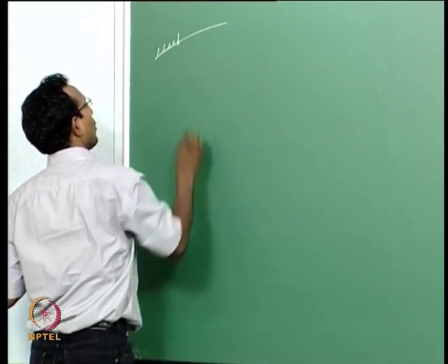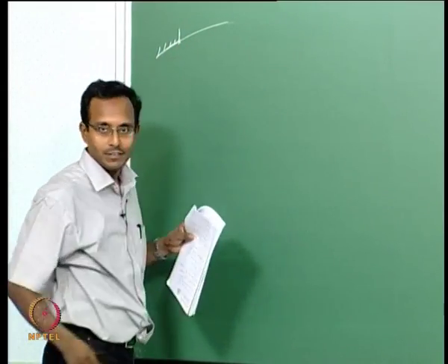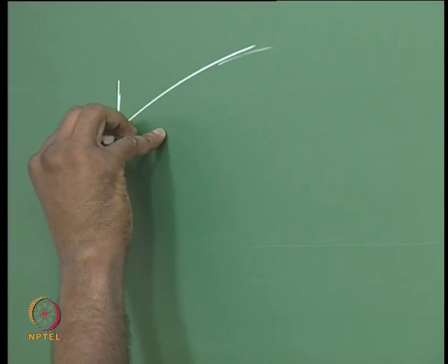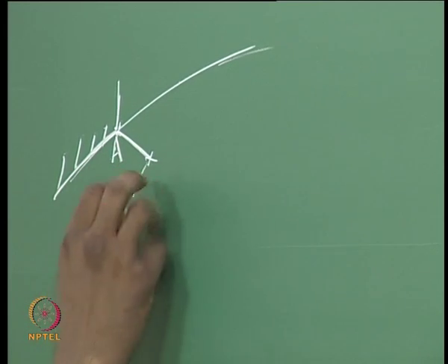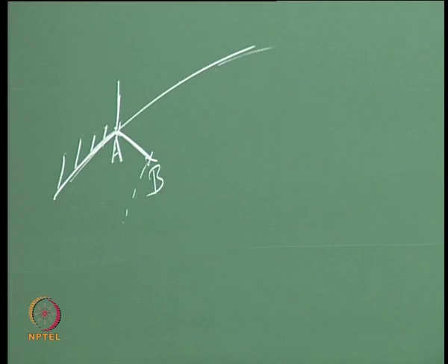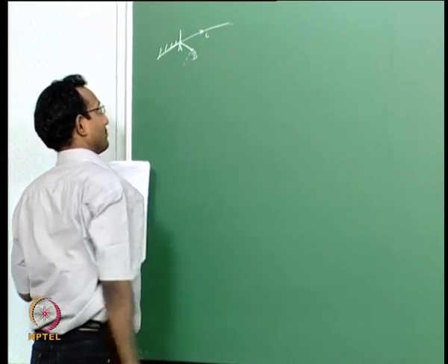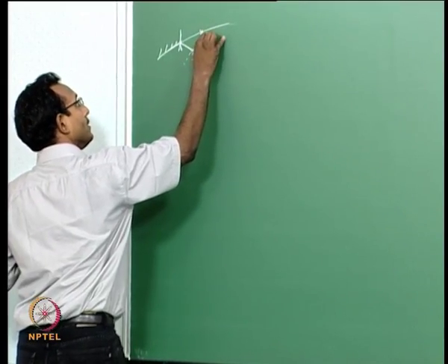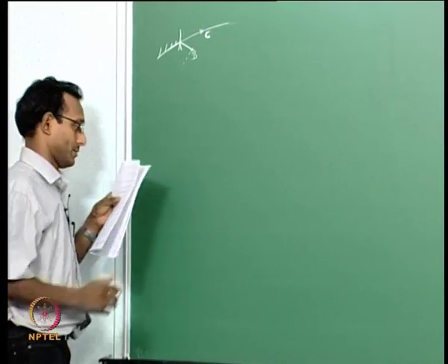and I know how to solve this, and suddenly there is a free jet going outside, and say I know this point A and I have already calculated from this side an interior point B, and now I want to find a point C on this. That is my goal. I want to find a point C on a pressure boundary of this jet. That is what we want.